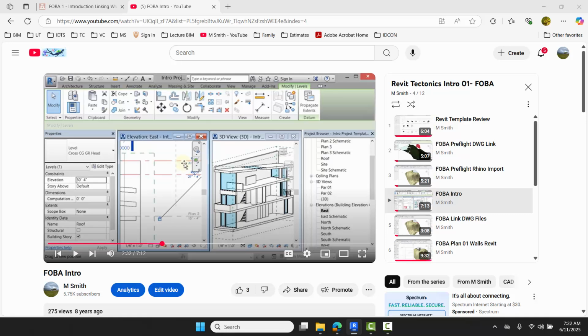If I were to adjust the roof level, which is kind of a funny level at 34 and 1 and 15, 30 seconds, anyway, let's take it down to 25 feet. Let's see if it'll squish it. You'll see everything associated with that roof now goes down. If I take it up to 35 feet, now it goes back up.